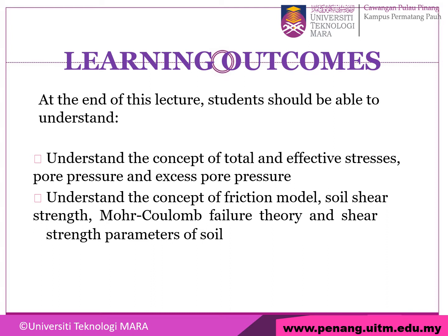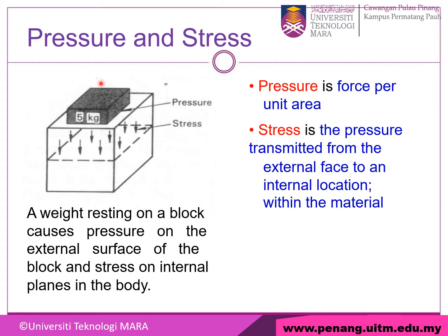At the end of this lecture, students are expected to understand the concept of total and effective stresses, pore pressure and excess pore pressure. Second, understand the concept of friction models, soil shear strength, Mohr-Coulomb failure theory, and shear strength parameters of soil. Alright, now we go for the topics pressure and stress.